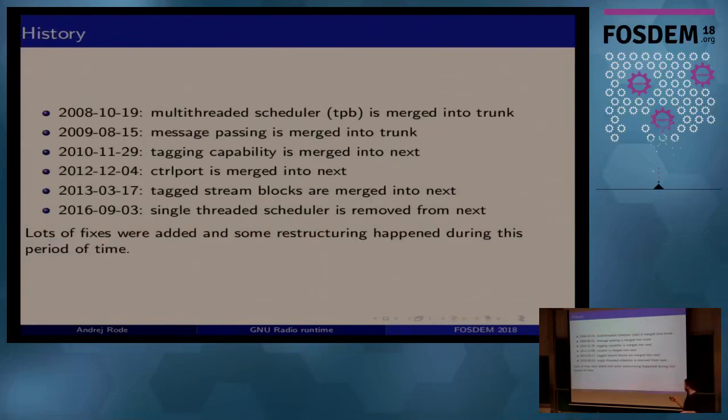Then also a very nice feature like the tagging capability was merged, so you can now add metadata to your samples, like which frequency, phase offsets you measured, to correct for them. So it was a nice thing. Then also control port. So this was added to introspect the flow graph, to have performance counters to see which blocks are performing well, which blocks are holding up the full processing.